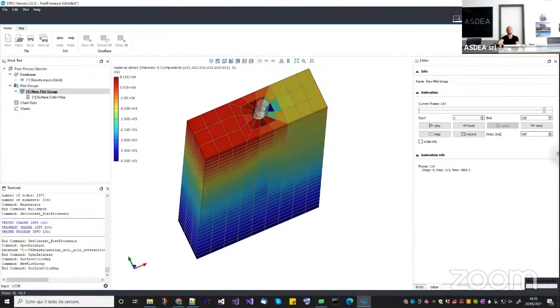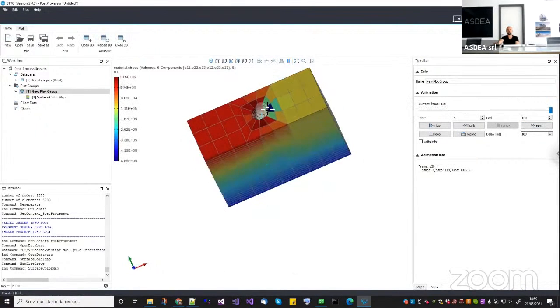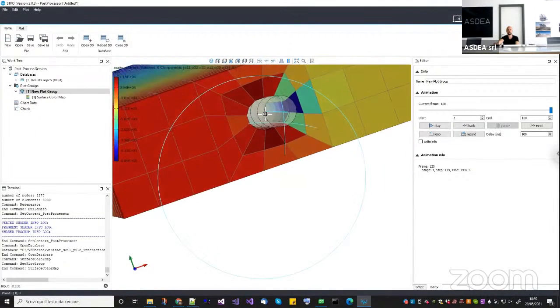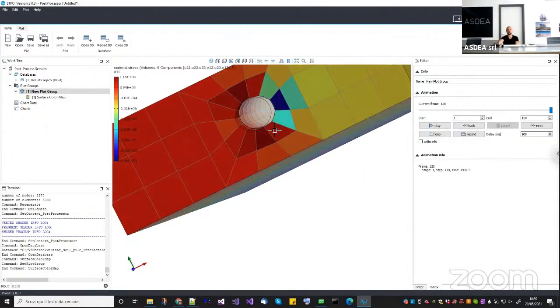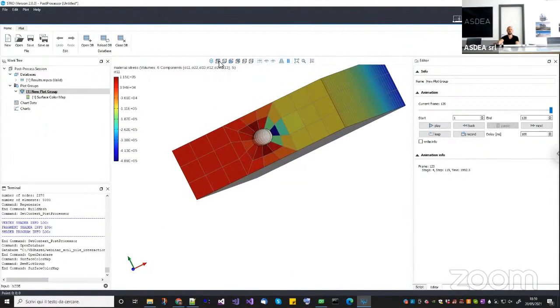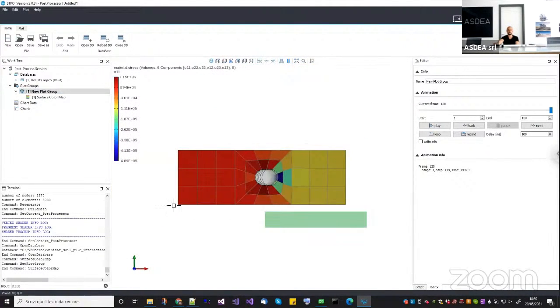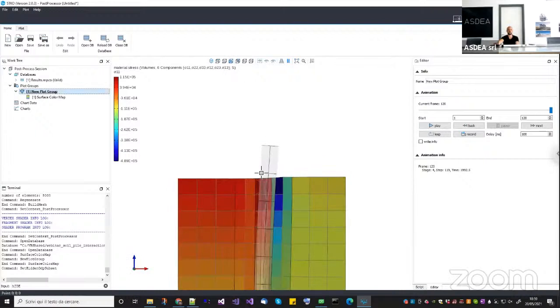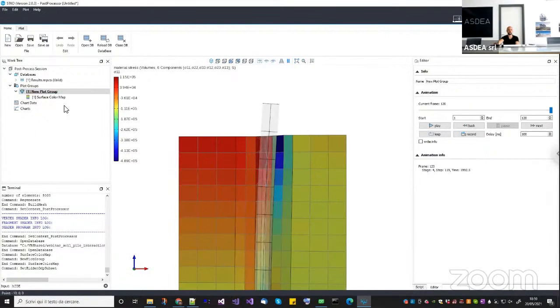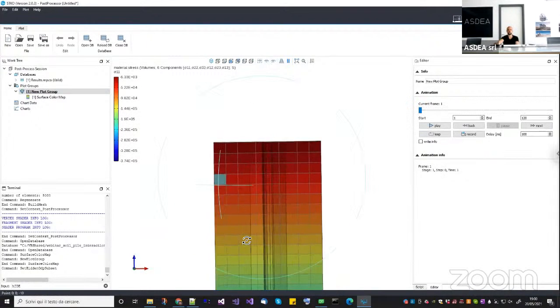The beam will push against the soil, as you can see from here, okay? And you can see the detachment here and the hard, normal contact on this side. Now, if you want to look better at what's going on, you can select some of these elements here, switch them off, put in a front view, and you can see what's going on here. Okay, so I go back to the beginning. So the full soil domain,